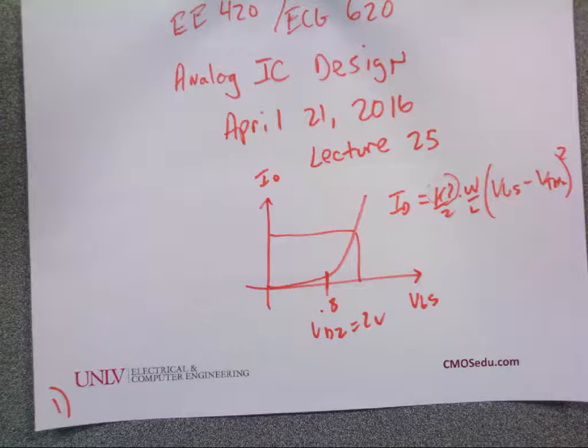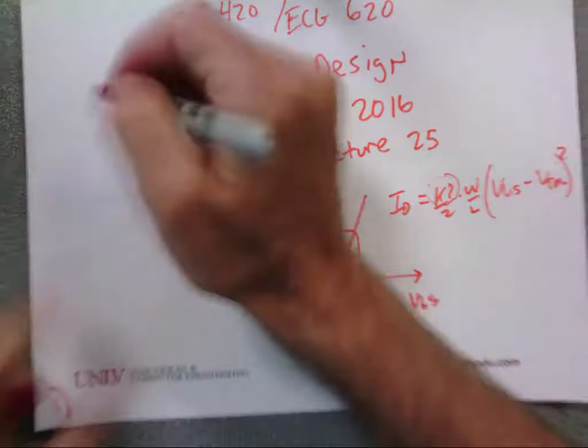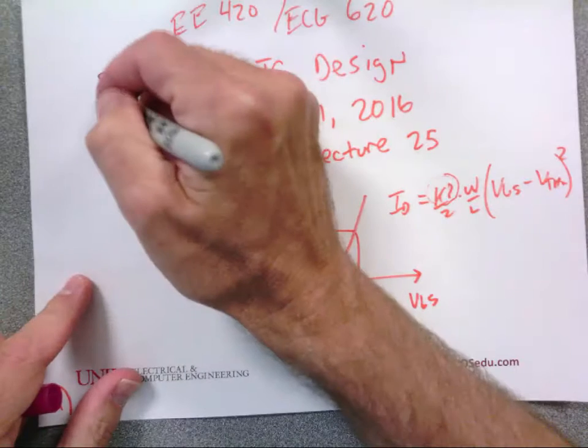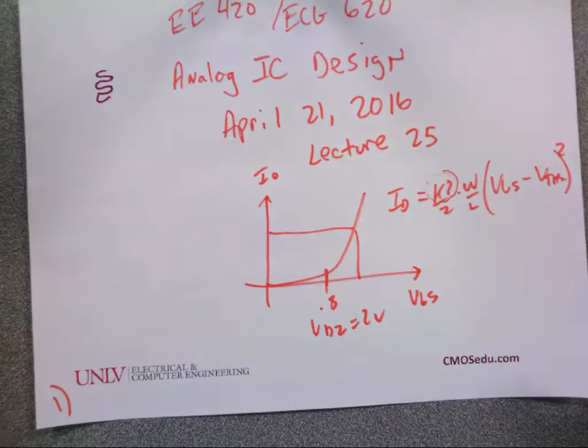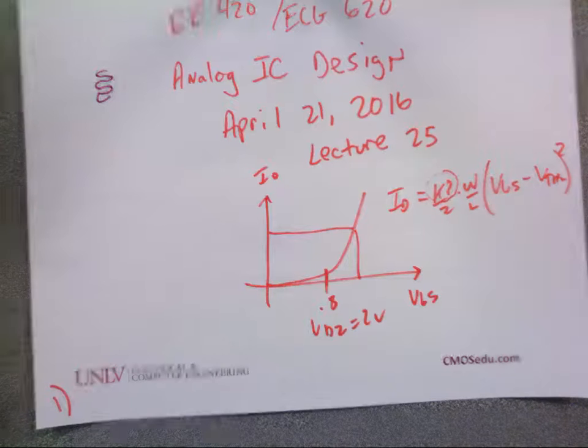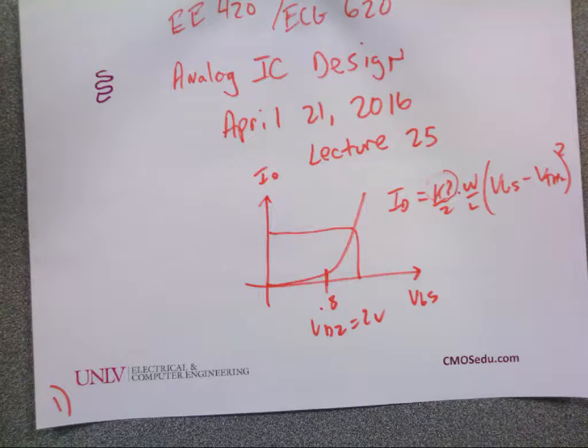So you'd have a channel length of 0.8 microns and a channel width of 3 meters. But if you take a piece of thread that's 3 meters and wind it up, it's really small. You can get 3 meters in easy, especially if the width is 0.8 microns. You just put them all in parallel.